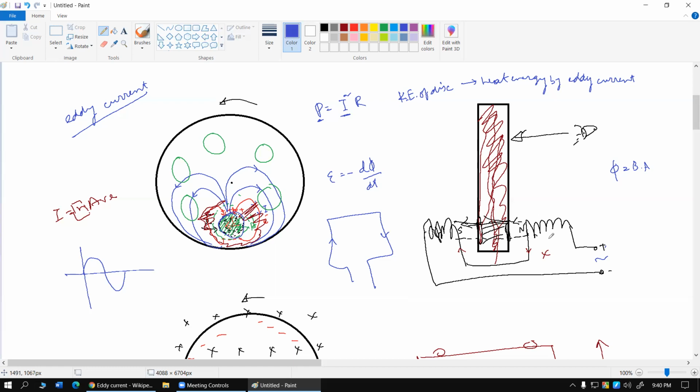So even if we apply an AC solenoid over here, the current will be back and forth. This specific direction that I've drawn, where the inside surface is positively charged and the outside surface is negatively charged, we're not going to have that. What we're going to have is back and forth oscillating current within the disk, and that heating effect can still be achieved. So if we use an AC solenoid over here, it's also possible for us to produce eddy current. I did not use an AC solenoid earlier for the sake of complication that I might not be able to transfer properly to you.